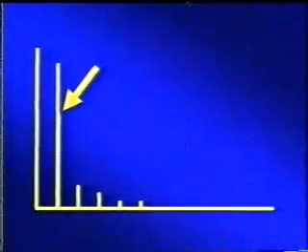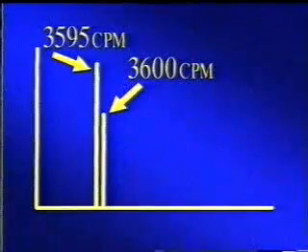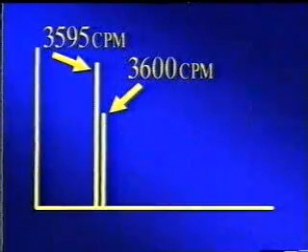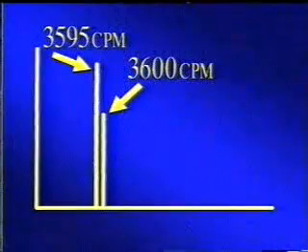This phenomenon occurs when two dominant peaks are close together, within 20 CPM, such as electrical line frequency at 3600 CPM and a shaft speed of 3595 CPM. Usually, the closer the two frequencies, the slower the phase walks. On frequencies this close, it is sometimes impossible to separate them to include only shaft speed.